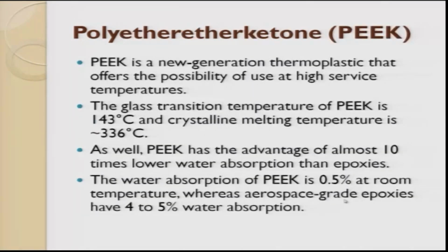PEEK is a new generation thermoplastic that offers the possibility of use under high service temperature conditions. The glass transition is 143, the crystalline melting temperature is around 336. It has the advantage of almost 10 times lower water absorption than epoxy polymer. So it can be used for several marine applications. PEEK is exhaustively used because it does not absorb water.